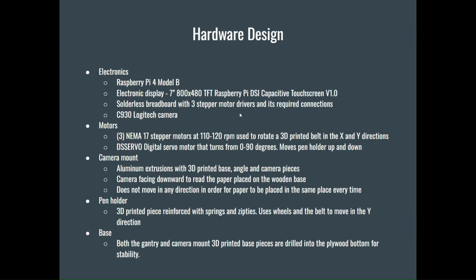And for our design that we actually did, we stuck with the Raspberry Pi. We used a 7-inch 800 by 480 TFT Raspberry Pi DSI capacitive touchscreen, so it would work well with the Raspberry Pi. We did create a solder breadboard for 3 stepper motor drivers, and we had the C930 Logitech camera, which fit our qualifications from before.